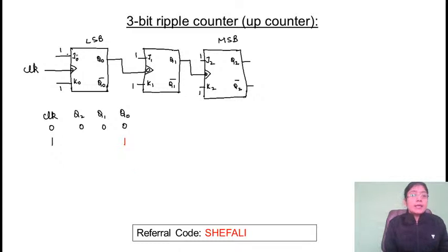First of all, let's understand what is positive edge triggering and what is negative edge triggering. Edge means the point where it changes the value, and if it is level triggering, the level is level 0 or level 1. But here we are talking about positive and negative edge triggering. So when is the value changing? Positive is when it is going from 0 to 1, when it is changing the level.